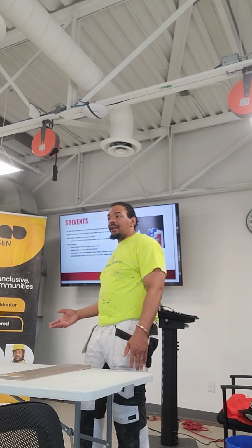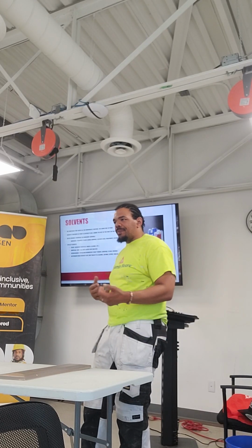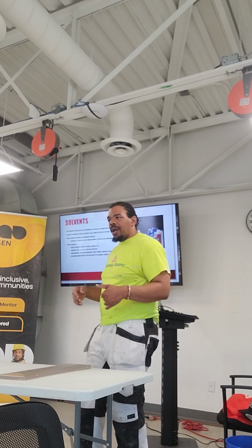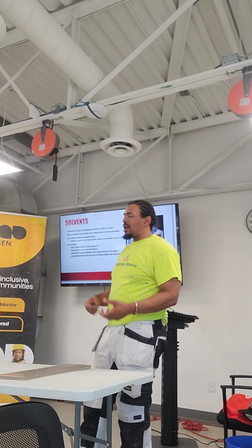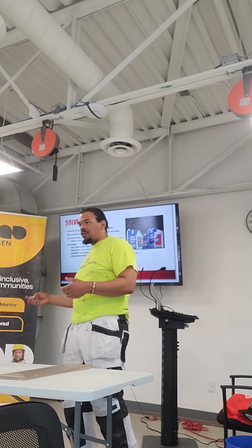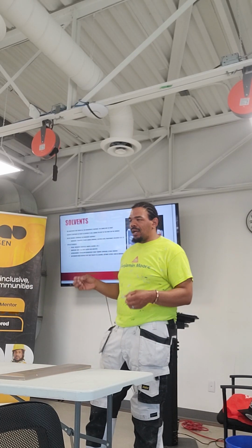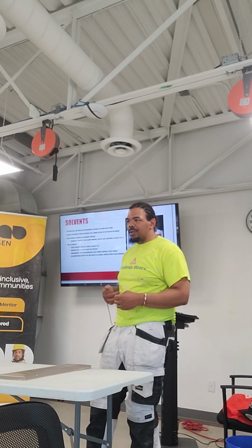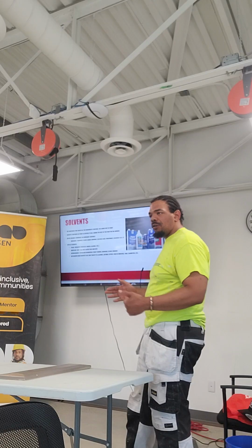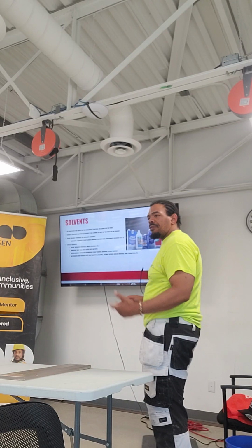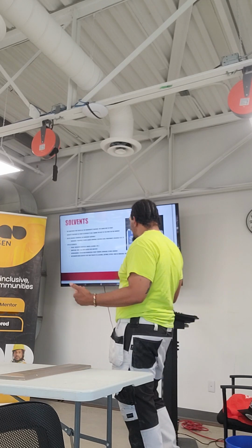Some people add water to their water-based paint. I don't like to do that because I think it thins out the color and it thins down the paint a little bit. But there are additives that you can use that are better suited for water-based paints than water. And they will not take away from the color, they won't take away from the durability. But they still give you all of the benefits of having an extra bit of solvent in your material that allows it to flow better. So paint solvents allow the paint to flow. So that's an important thing.